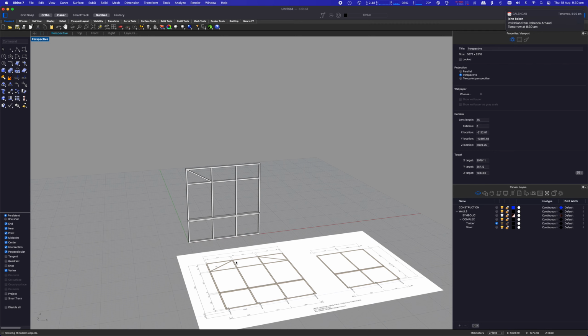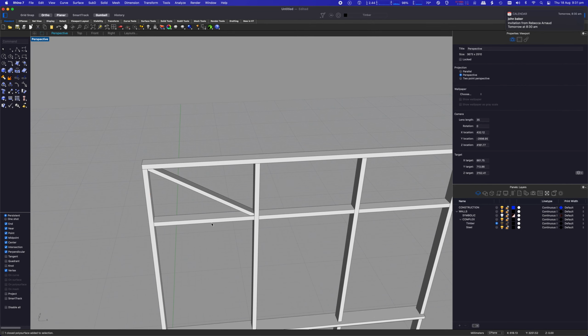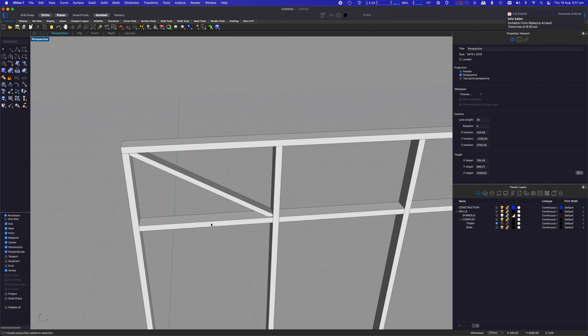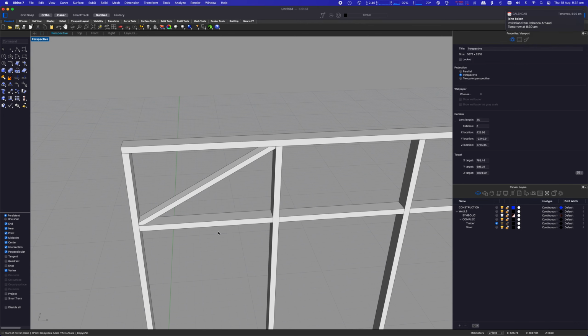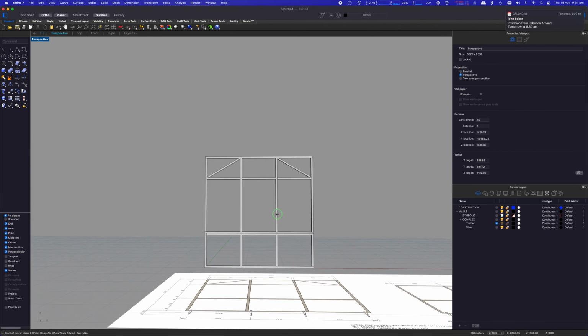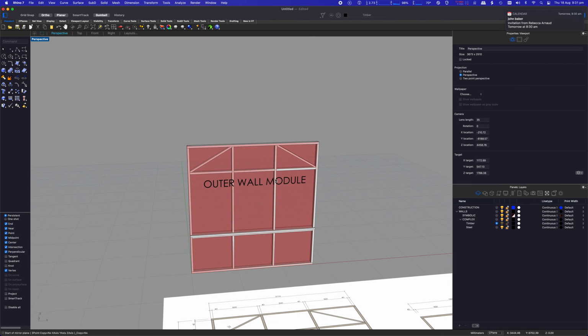But what have I done? I've drawn it backwards. Luckily, I can just mirror it. Now, this is a handy thing to mirror in because it's exactly the same width, so I can just go select, mirror, midpoint, across. All right, so that's better, and then we'll use mirror again, but we'll use the middle of this, and we'll turn on copy, and we'll go there, there. So there's our structure. We can turn our symbolic stuff back on if we want.